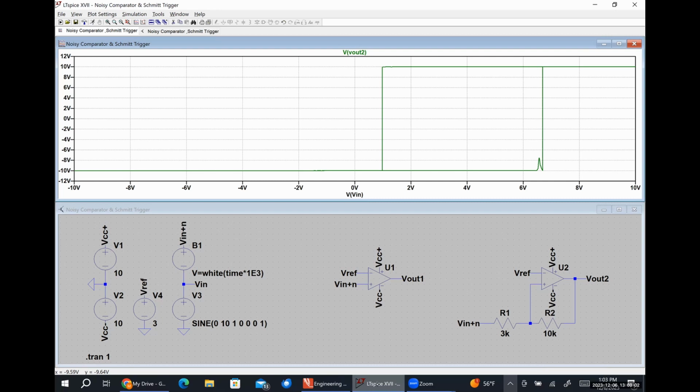All right, so we have determined that our lower trigger limit voltage mathematically is 0.9. Looking at this graph, that looks like a pretty good estimate. Let's see if I can pinpoint things here.